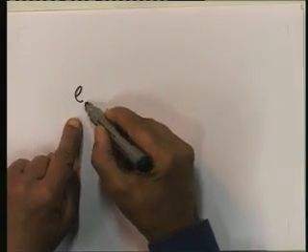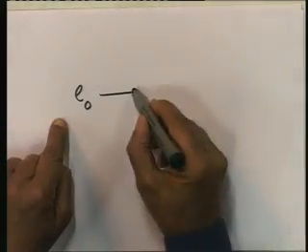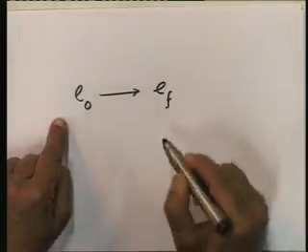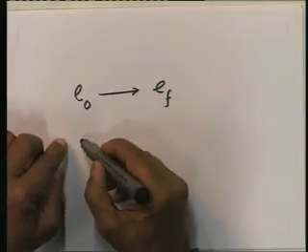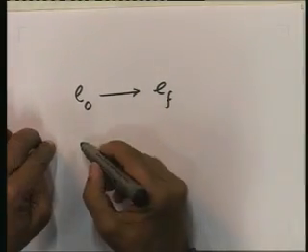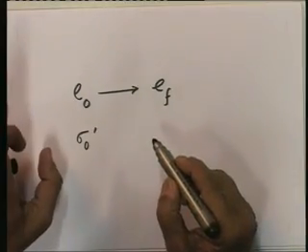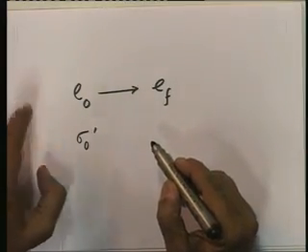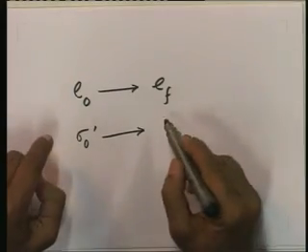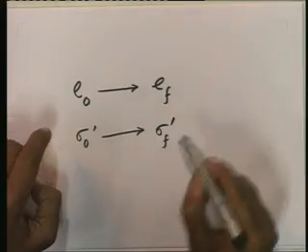To put it briefly, we said that this compression, the total compression that is going to take place is dependent upon the change of void ratio, which let us say is e0 to begin with and changes to e final during the application of a load, which in terms of stress may be considered as sigma 0 initially, sigma 0 dash if we consider the effective stress, and which increases to sigma final effective.